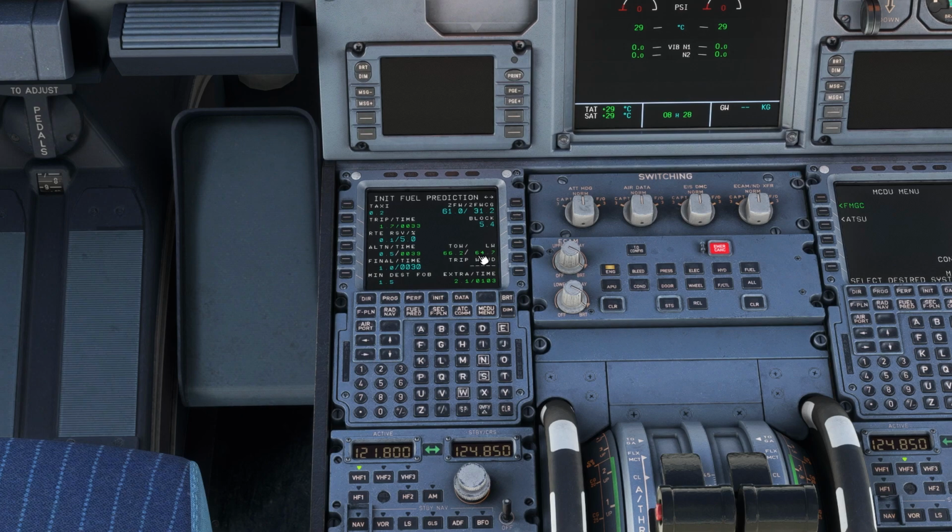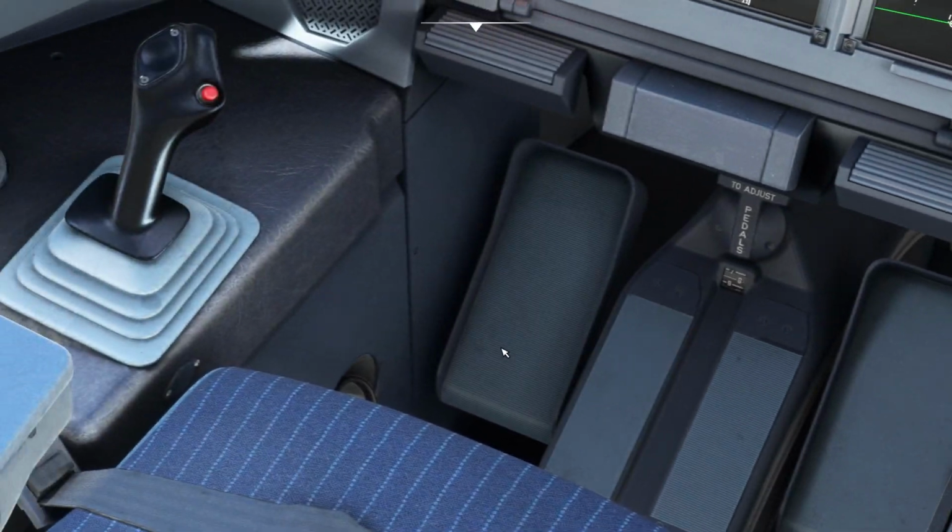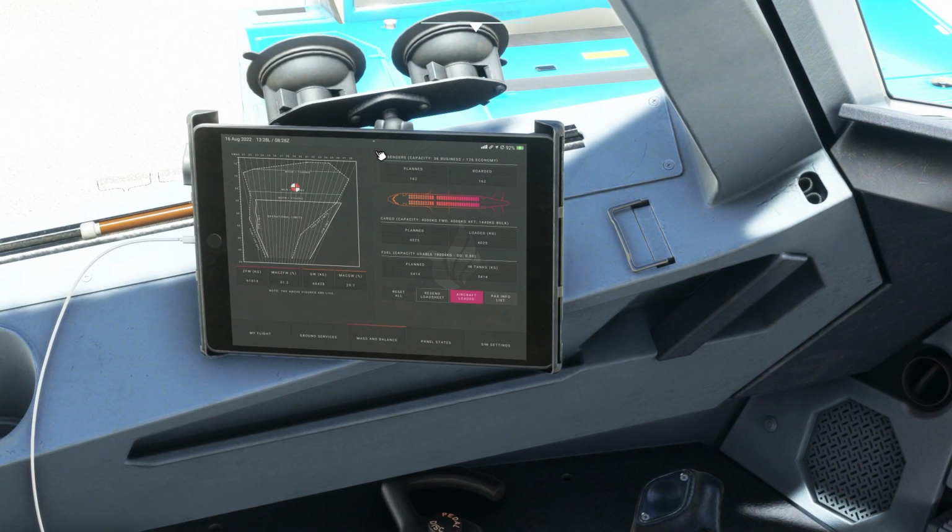We have to use this information while landing at the airport. I will tell you how to use this information, but remember this point, that the landing weight is 64.7 after the fuel burned. For the reserves and alternate, everything is coming over here. And the last thing that we have to do is calculate the takeoff performance. The best thing about the Fenix Airbus A320 is that it has its own takeoff performance. This is for the takeoff performance and this is for the landing.